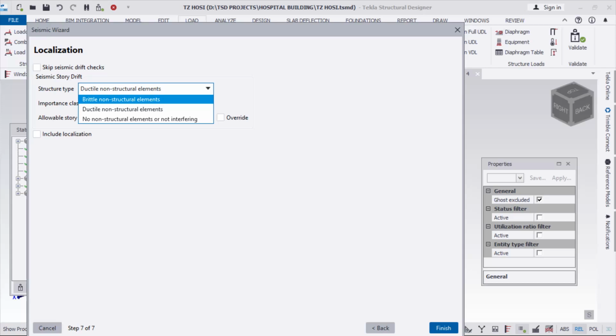So in this case, it assumes that these elements do not add any lateral strength but can change stiffness slightly. So the best time to use this kind of option is when we have, like I've mentioned, the masonry frames or old RC structures or any structure with brittle behavior and that has walls that might attract some seismic forces.